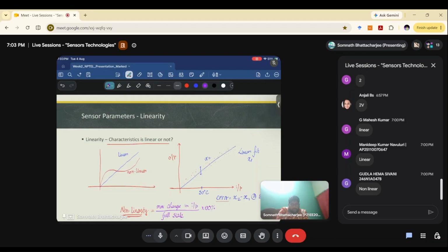So the hysteresis is also programmable based on the voltage you give it. So if you are giving very low voltage, that is 0 volts or something like that, apart from the polarity of the voltage itself, the hysteresis is very high. But when you are giving it a very high voltage, that is 2.5 volts or negative 2.5 volts, based on the device polarity and everything, you will get a low hysteresis.